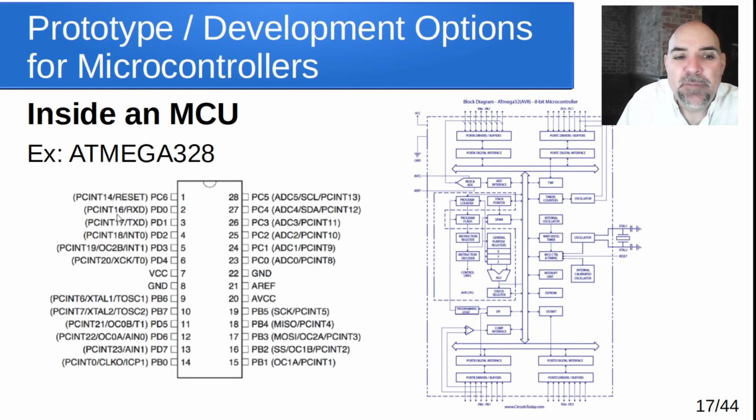Here we have the same pin change on those, but receive and transmit for serial communication. This can act as an interrupt. This can act as another interrupt. Here's one that is OC2B, that's an output compare 2B, that's for a timer counter channel. But you'll notice every one of these can have these alternate functions. Like here's analog input 0, analog input 1. Another output compare. Here's SCK, MISO, MOSI, and slave select, that's an SPI interface. Here's SCL and SDA, that's an I2C interface. Here's more A to D converter channels up here.